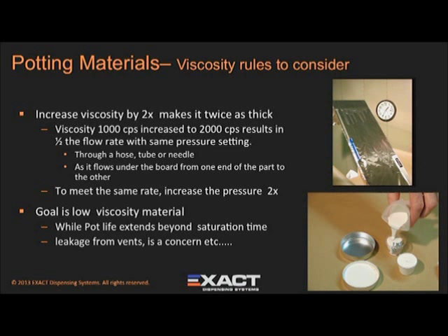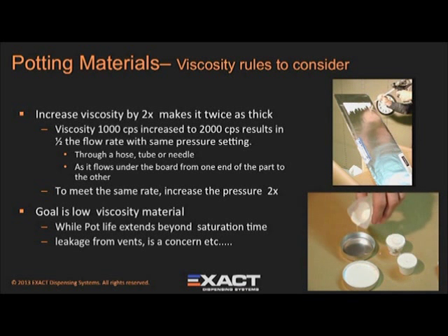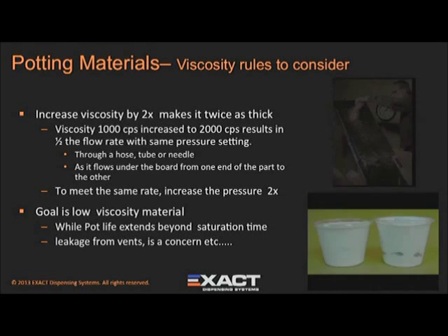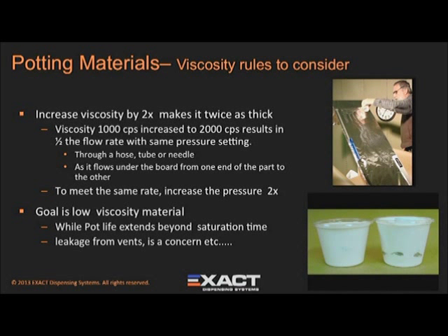We suggest the goal is to have the lowest viscosity material possible while still meeting your other product needs, like saturation rates within your part. As you can see in these videos, as viscosity increases while the material is going through its pot life, the ability of the resin to flow changes, which impacts the quality of the final part.